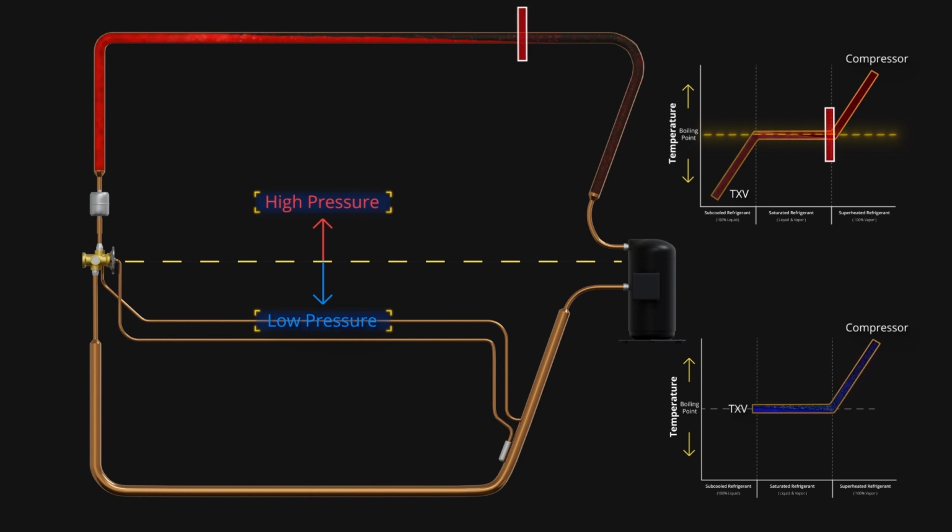As more heat is rejected, the refrigerant undergoes a phase change without any change in temperature. The saturated refrigerant condenses to 100% high-pressure subcooled liquid. The high-pressure subcooled liquid refrigerant moves through the metering device, rapidly reducing its pressure. This sudden pressure drop causes the refrigerant to expand and cool rapidly, transforming it into a saturated low-pressure, low-temperature refrigerant.